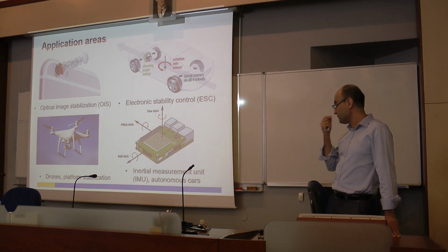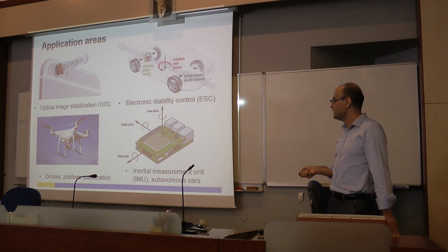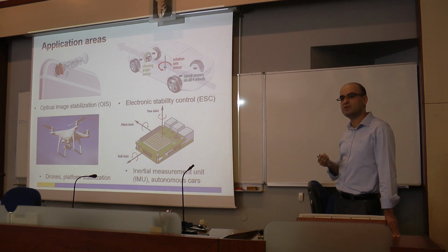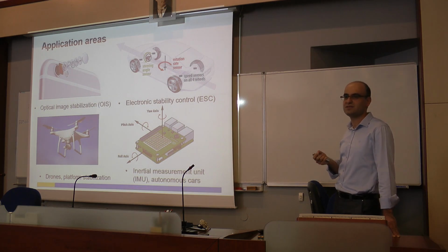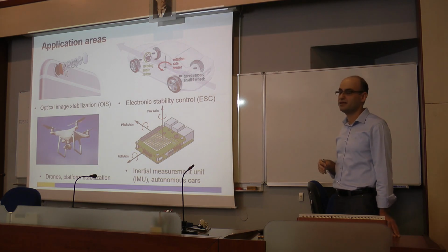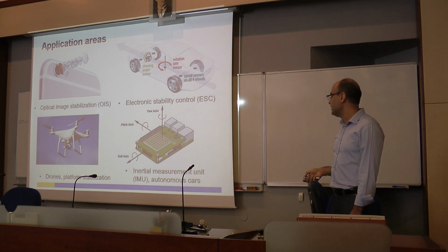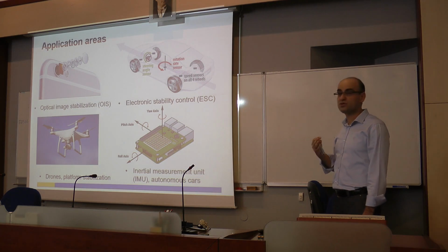Inertial measurement units: when you have 3 gyros and 3 accelerometers, then you can measure X, Y, Z rotation and linear acceleration, and you make an IMU. Ideally, when you are navigating, you use GPS. GPS can be jammed, but to misguide the gyro or accelerometer, you have to change the gravity. These things are very robust, but the problem is they are not as accurate. They drift with time, and in navigation you take the integral of the gyro and accelerometer, and the errors build up.